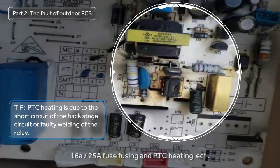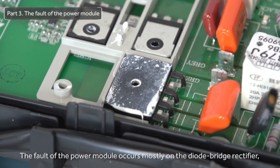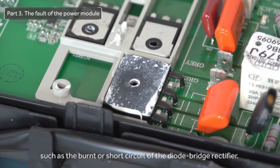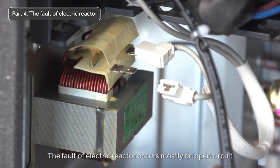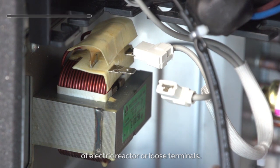heating, etc. Part 3. The fault of the power module. The fault of the power module occurs mostly on the diode bridge rectifier, such as the burnt or short circuit of the diode bridge rectifier. Part 4. The fault of electric reactor. The fault of electric reactor occurs mostly on open circuit of electric reactor or loose terminals.